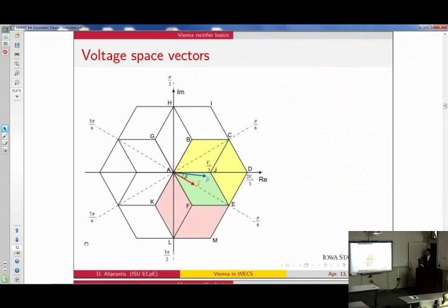Yeah, please do. So I'm trying to explain to you how inverters work in one slide, but it's kind of impossible. But the idea is that you can get any voltage here by appropriately switching the things on and off, deciding which ones to switch and how long to keep them on. So you take, let's say, 30% of this point and 40% of that point and another 30% of that point, which gives you some kind of average voltage inside that triangle.